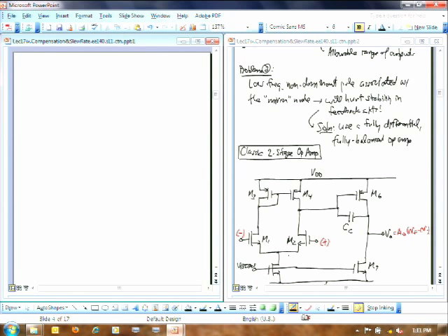All right, so back to this. Let's get the gain of this thing, and we're going to get the gain the same way that we've always done it. We're going to do it stage by stage. Let's get the first stage gain, meaning I want the gain up to this node here, which is node 1. I want the gain from these two inputs to node 1. The first stage I'll call AV1, say that's V1 over V sub I.